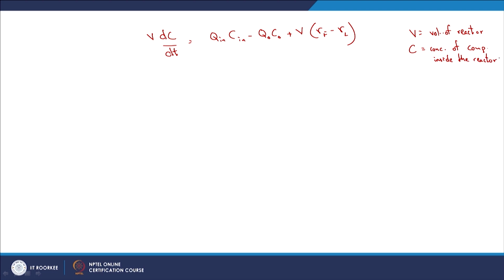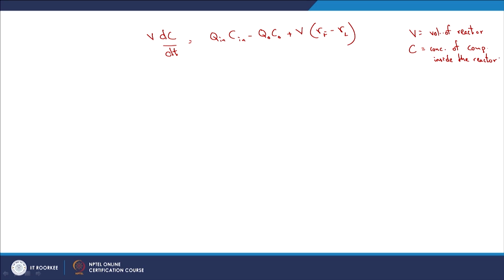Right. So obviously now, as you see here, the fundamental assumption, not maybe, that's apparent, is that the concentration within the reactor is the same throughout the reactor, right. That is what you see here: the concentration is only changing with time, not with space. So that is one aspect, and we will come back to that later. So Q in and Q out are the flows coming in and out of the relevant fluid, right.